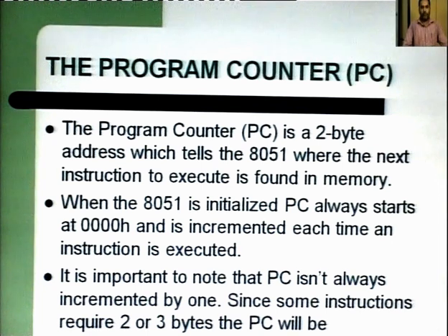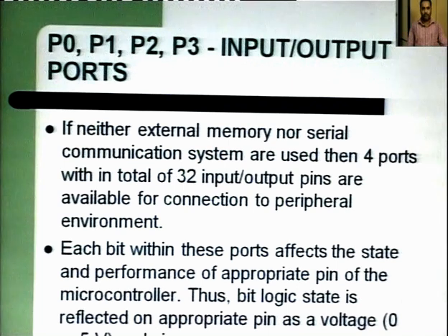The program counter is a 2-byte, 16-bit register, which tells the 8051 from where the next instruction is to be executed. Initially the program counter is initialized to 0000, and from then on it is incremented by 1, 2 or 3 bytes, depending upon the instruction size.